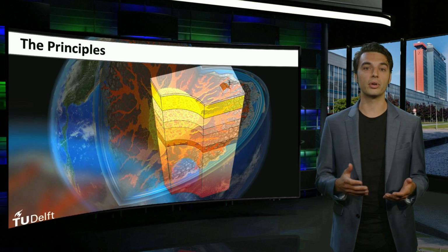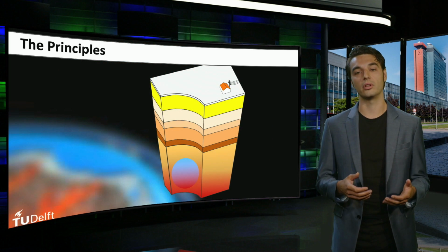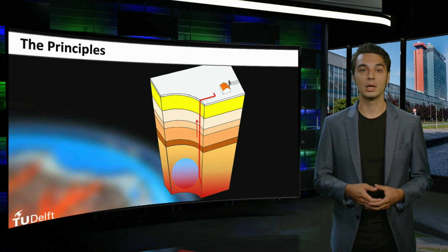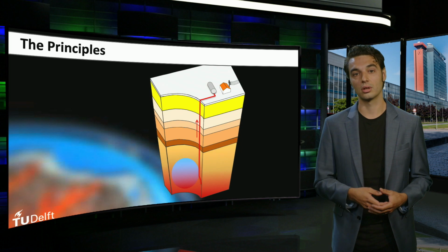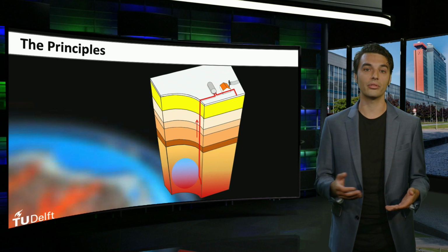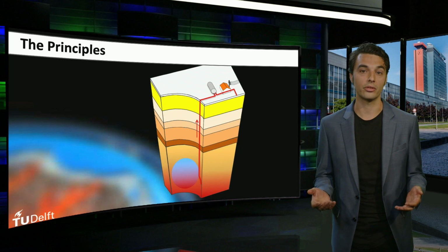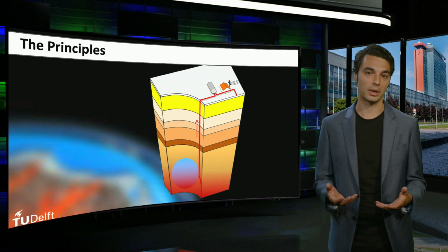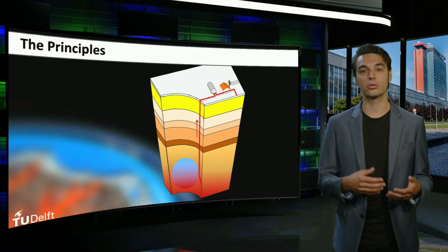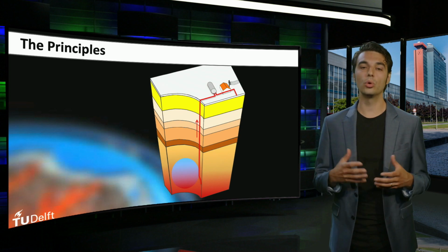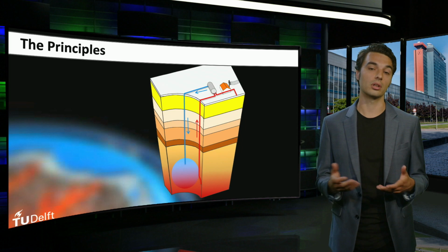The general principle of geothermal energy is relatively simple. Hot water is pumped up from an underground reservoir. The heat in the groundwater is extracted with a heat exchanger. That heat is then used in a similar fashion as in a solar thermal plant, a biomass plant, or a nuclear power plant, using a conventional steam turbine and generator to convert thermal to mechanical energy and then to electrical energy. The cooled water is re-injected in the ground at a different location.